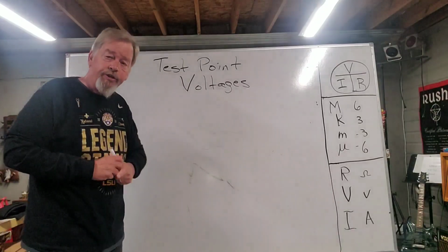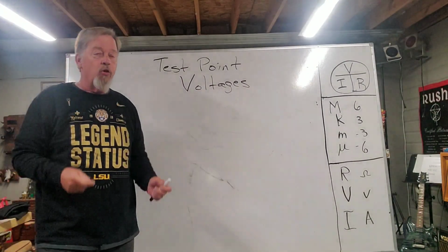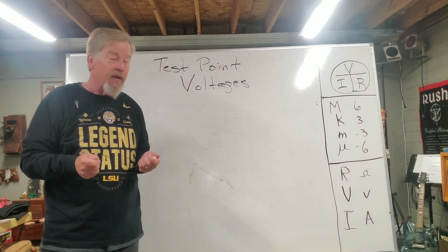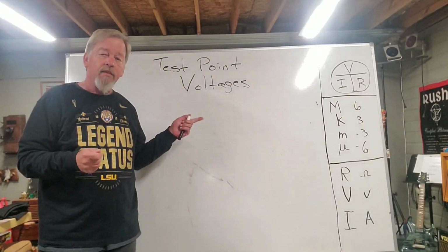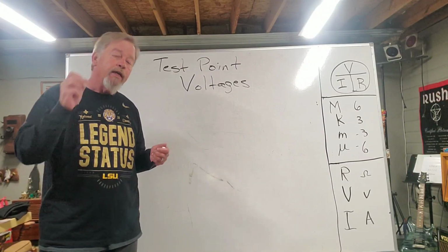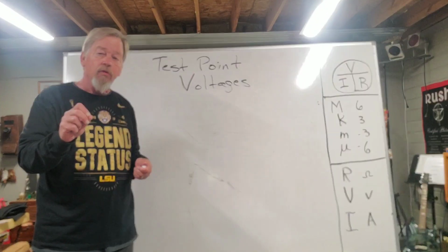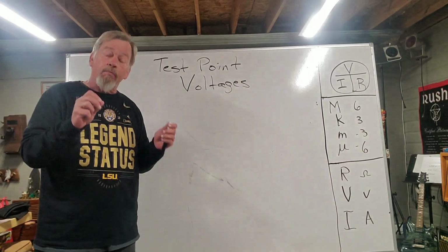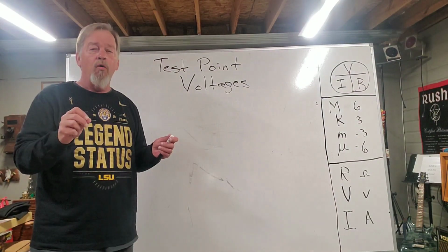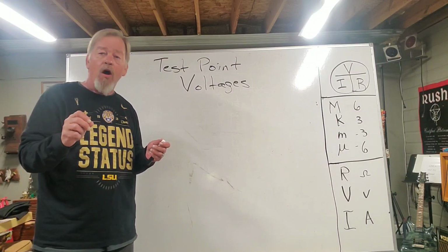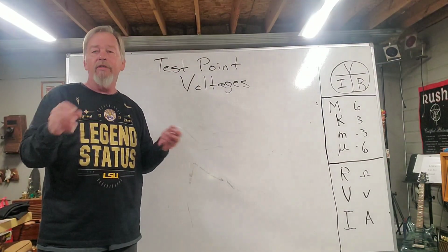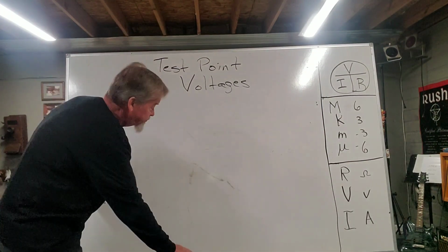is how to measure test point voltages. So the meter has two leads on it, okay? Now the test point, since that's the point that I want to measure, is where the red lead goes. But the thing is, where does this black lead go? Well, the test point is always referenced from ground, so the black lead goes to ground. Now ground is defined, hold on.